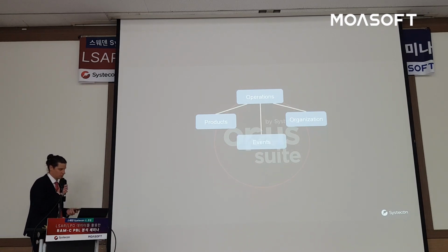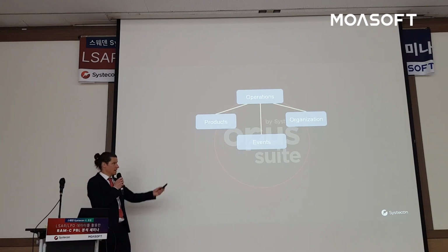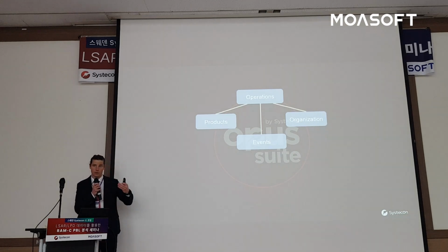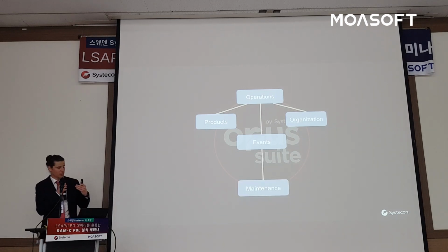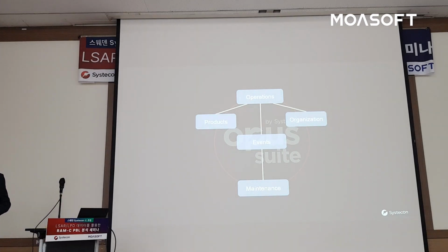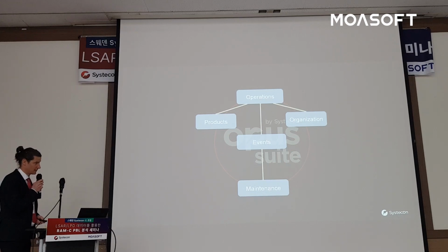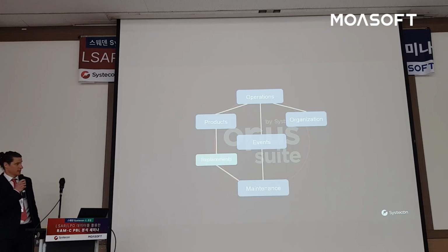And of course, when we start to operate with the systems, things will happen. They will fail, they will break. We use the concept of events, and events can be random, so unforeseen failures. They can also be planned events according to a maintenance schedule. But what's common with all the events is that the system becomes inoperable. We have to stop with the system and do something with it before we can go out sailing or flying or whatever we're going to do. So we need to perform some kind of maintenance. This maintenance often leads to a replacement of one of the parts in the product.